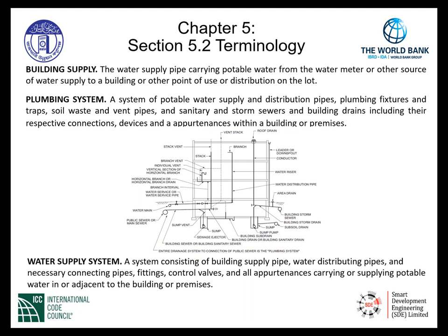This is our storm sewer system. And as we can see here on the right-hand side, outside of the building, is our building storm sewer. This is a point that collects the water, in this application, from the roof drain. We collect the water, rainwater, from the roof through roof drains into vertical pipes that we call conductors that then connect into the building storm drainage system.